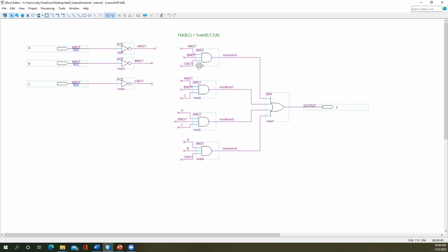And then I'm using named wire connections, right? Named each one of these wires here, right? And over here on the AND gate, so product of sums, right? The AND gate forms that product form. And so we would have then this AND gate here for minterm 0, where we've got A naught, and it with B naught, and it with C naught.